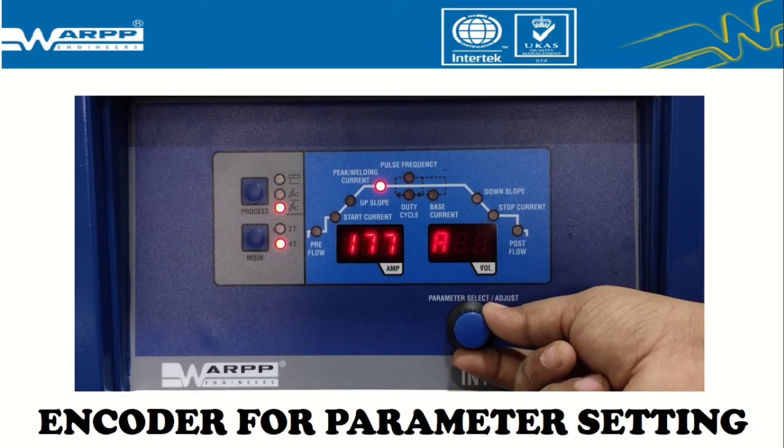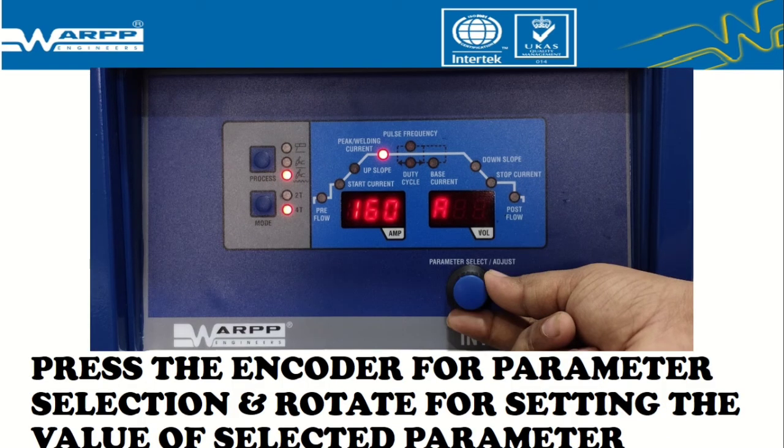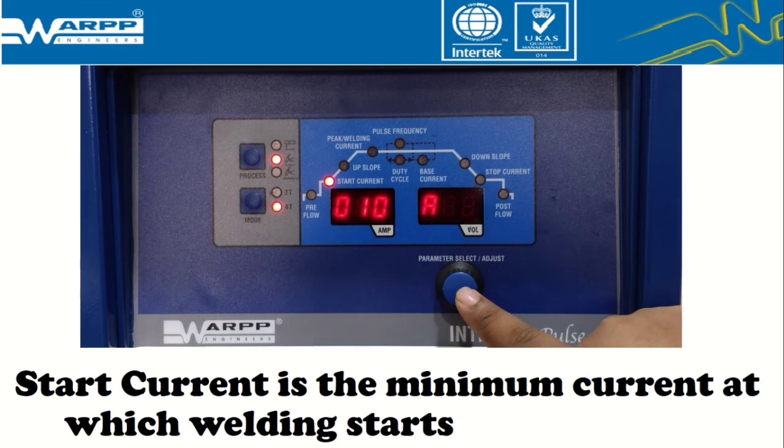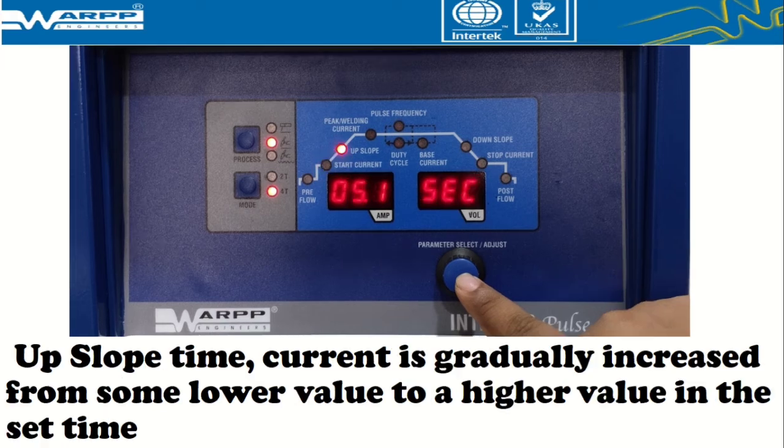This is the encoder for parameter setting. Press the encoder for parameter selection and rotate for setting the value of the selected parameter. This is pre-flow time. It is the time of the gas flow before welding. Start current is the minimum current at which welding starts. This is upslope time. Current is gradually increased from some lower value to a higher value in the set time.